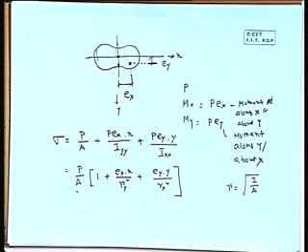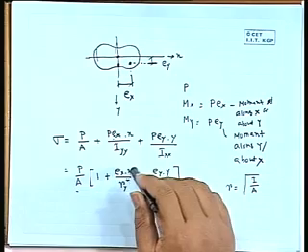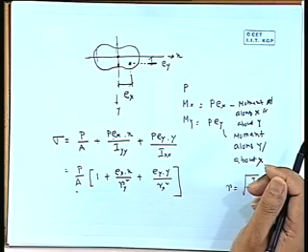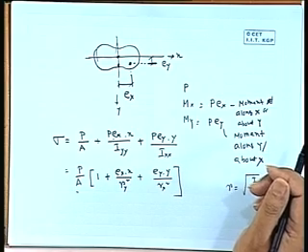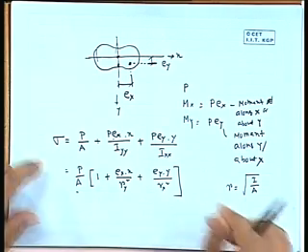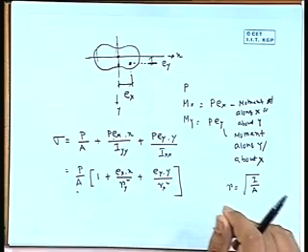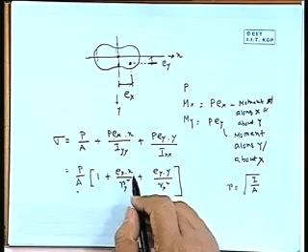Now, that is the general expression. If we want to express the stress at the extreme fiber, this x we can write as, say, C1x, this is C1y, and at the other end it is C2x or C2y, right. So, for some specific case we can write the extreme values. Now, here we can take the example of a rectangular section and try to see what is happening. So, sigma equals P by A into 1 plus Ex x by ry square plus Ey y by rx square. This is the maximum stress. This is the stress at any point x, y.